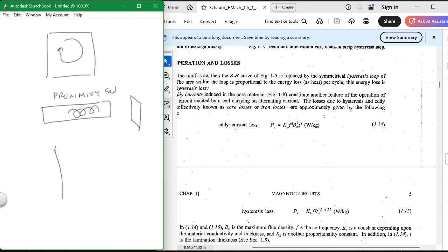If you look at the cross-sectional area of the rotor of a motor that's spinning, here's your axle right there, and then you've got these long pieces where there's a metal with windings on it, and in between them you've got these pieces of insulation. Why do you do that? To cut down on the eddy current. If you have an insulator there, you can't have a big swirling eddy current, only these little bitty ones.